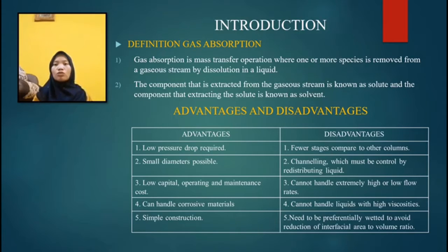Second, channeling, which must be controlled by redistributing the liquid. Third, cannot handle extremely high or low flow rates. Four, cannot handle liquid with high viscosity. And five, needs to be properly wetted to avoid reduction of the interfacial area to volume ratio.